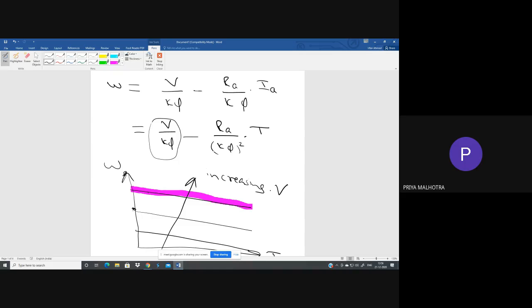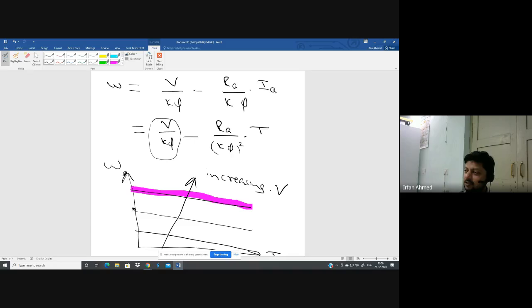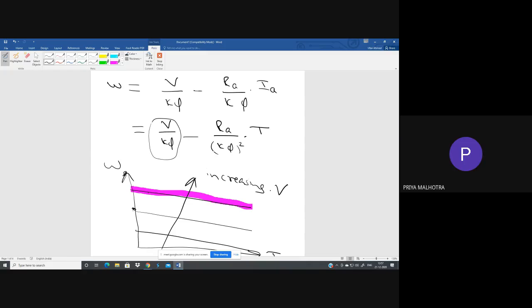So you are saying speed can be increased up to 2 to 2.5 times, so we can decrease the flux in the same proportion. Suppose I have the facility of increasing speed about 2.5 times also. I'm using very high quality materials, so I don't have any limit. So how much can I decrease the flux? In the same proportion, we can decrease our flux.